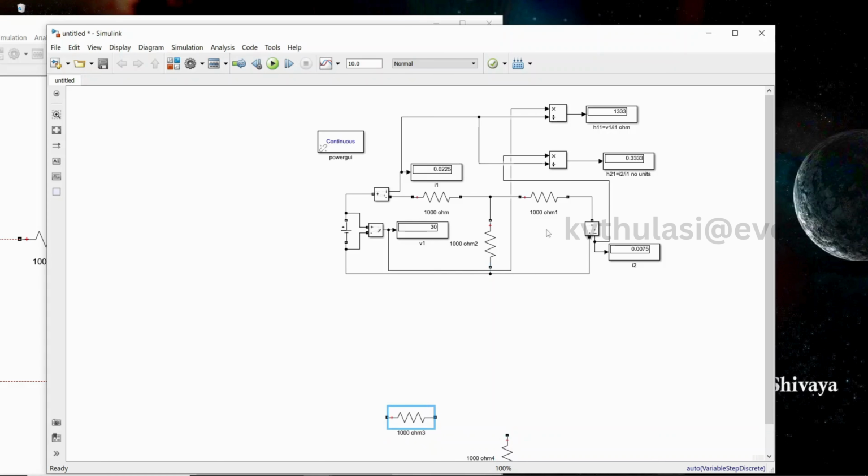These are the elements, and this element also you copy and paste here. And this voltage source: you can see here the input is open circuited, so you don't need to connect the input, and we have to excite it only at the output. Just copy it, place it at the output side, take this voltmeter also, and let's try to connect. And we require one ammeter. Take this ammeter at the output port and connect it.